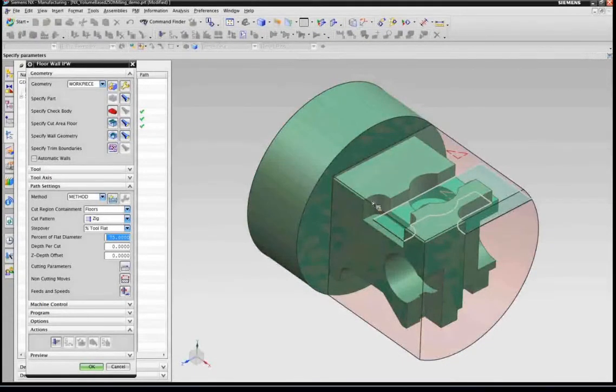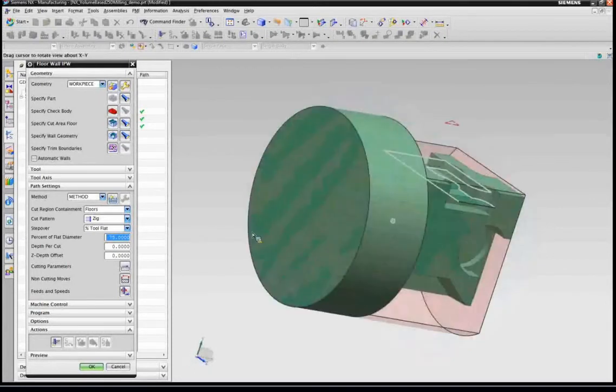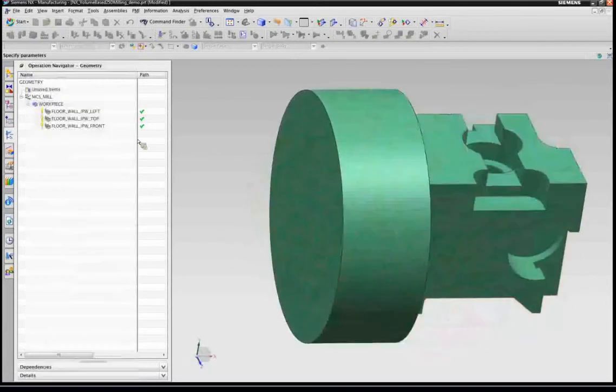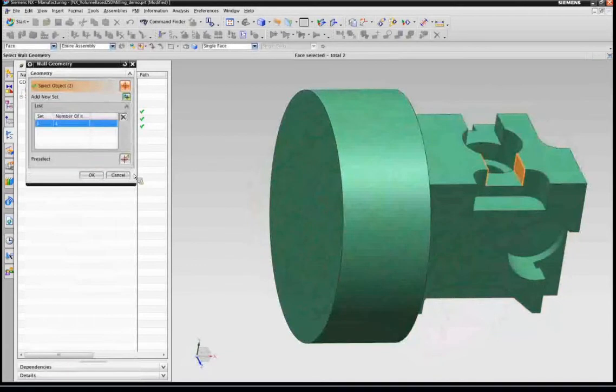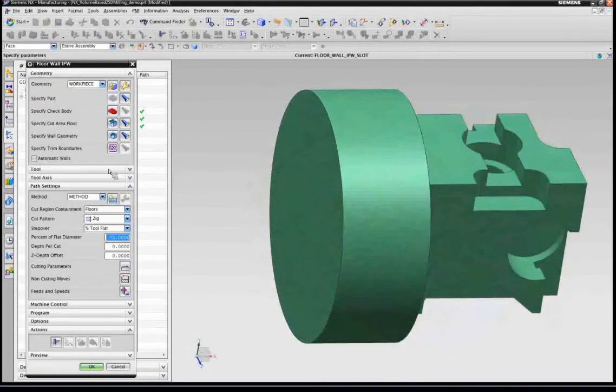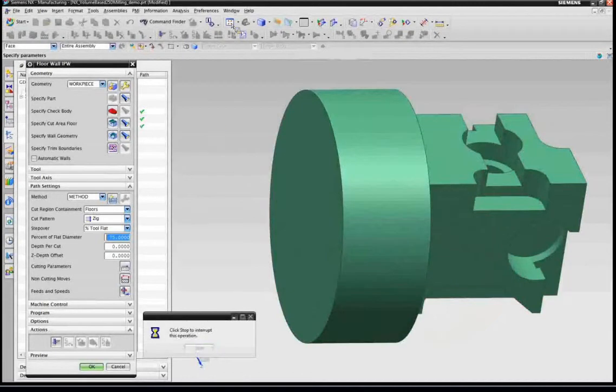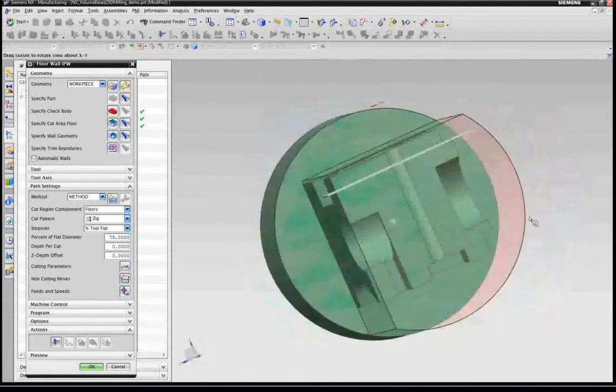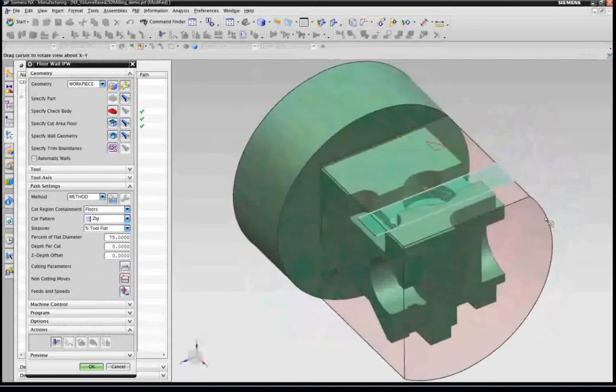I'm not cutting anywhere in this area. I'm not going in there. I'm extending my walls and I'm closing any gaps. And obviously, you pretty much figured out that I can do the exact same thing by selecting another wall on the opposite side, and that will give me the result I showed you initially, right?